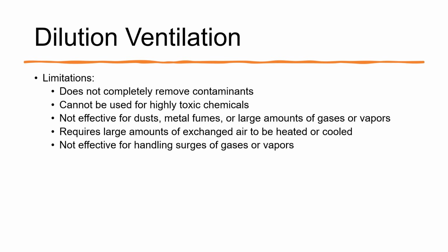There are some limitations to dilution ventilation. So dilution ventilation is great, like I said, because it is simple, it is often very cheap, and it's pretty easy to do. However, when used to control chemical pollutants, dilution must be limited to situations where the amounts of pollutants generated are not very high, their toxicity is relatively moderate, workers don't carry out their tasks in the immediate vicinity of the source of contamination, and the emission rate of contaminants is relatively uniform.